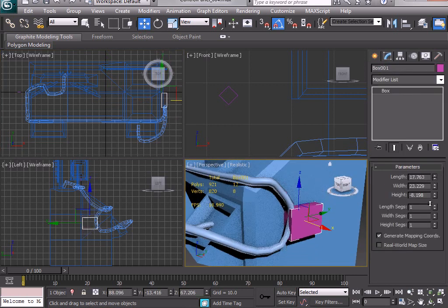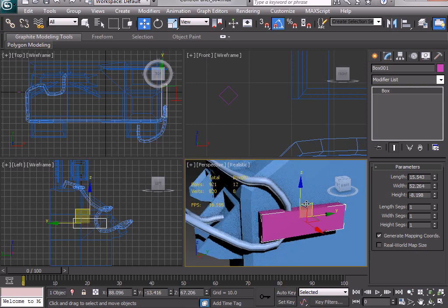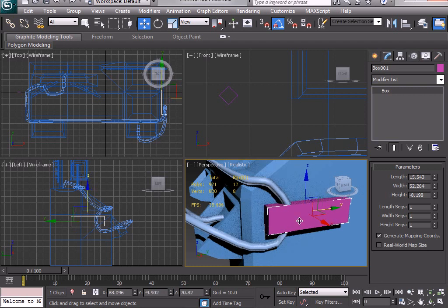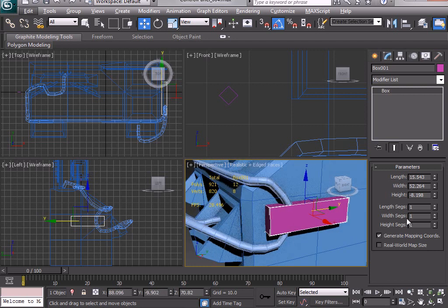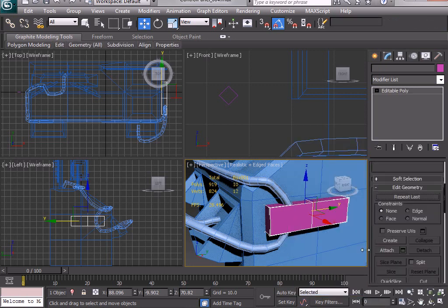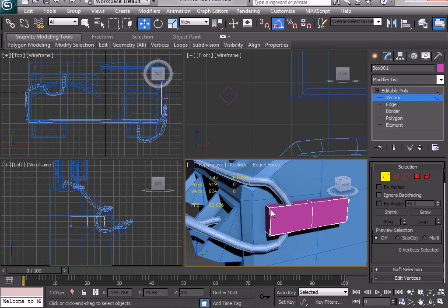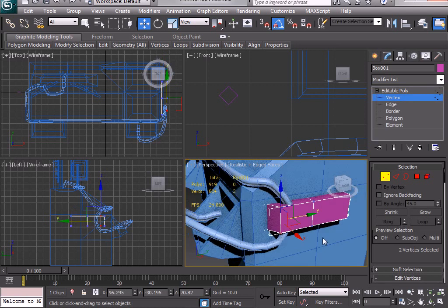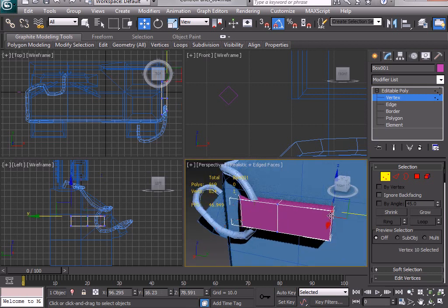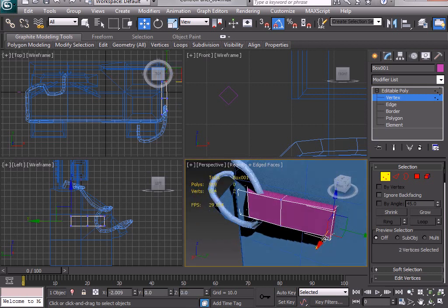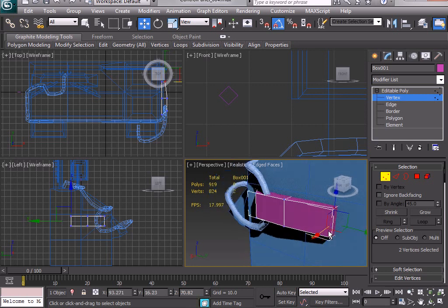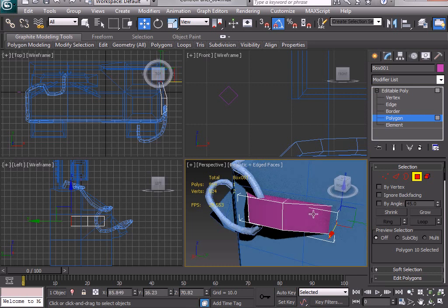And even this simple section that we can add on here should add a lot to it and sort of keep the whole thing compliant. I'm going to add in this segment, convert this to an editable poly. We grab these vertex back a bit. I might actually just pull that whole thing so it's inside the other mesh.